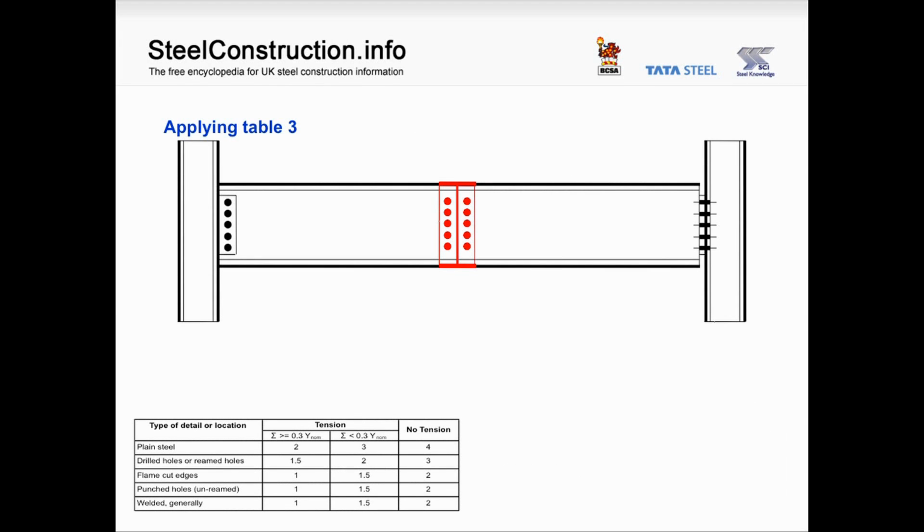So here we have a primary beam, thin plate to the left hand side, flexible end plate to the right hand side, and a bolted connection at mid-span from an incoming beam. We need to know a little bit about fabrication processes, and I'm going to make some conservative assessment about stress levels. Now most fabricators have a cut and drill line, so our beam will have saw cut ends and the holes will be drilled. Let's consider the left hand side.